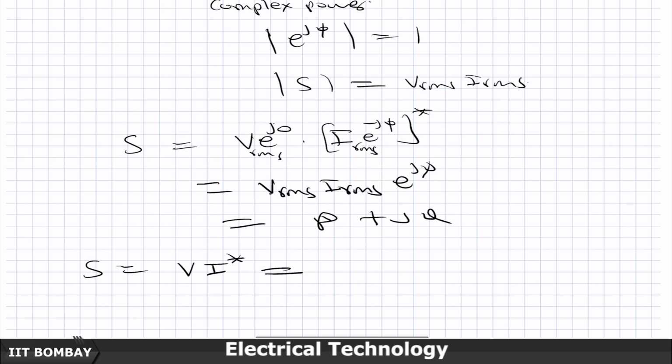Reactive power consumed actually does not do any active work, to be very honest with you, but you get used to this terminology. And the reactive power consumed by an inductive element should be positive. With that convention, this notation of complex power V I star has come out.